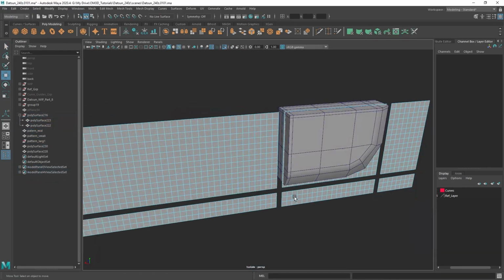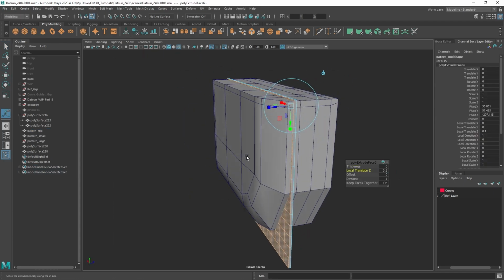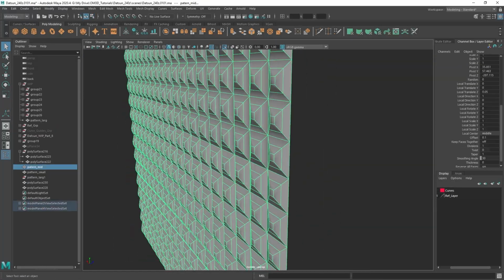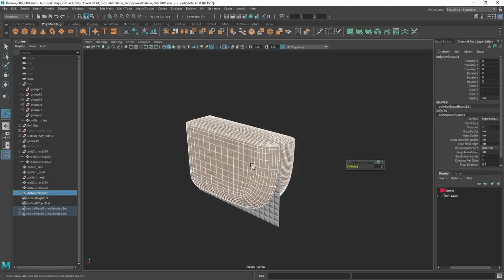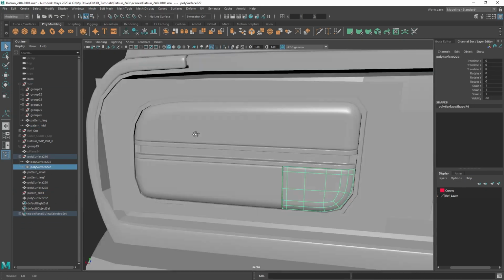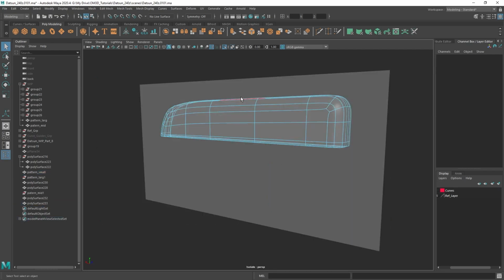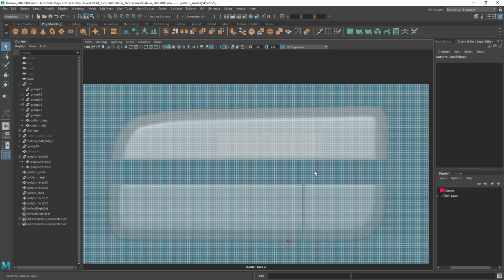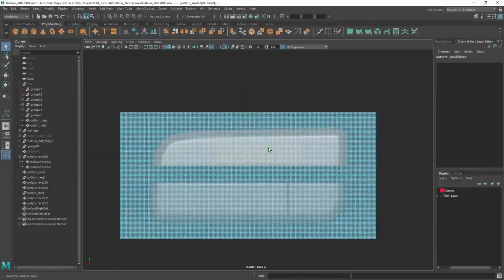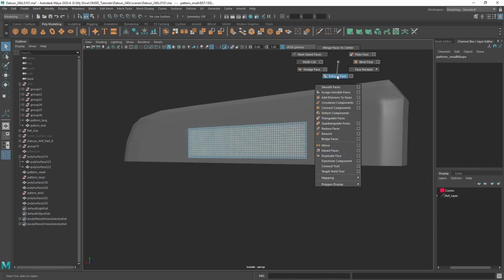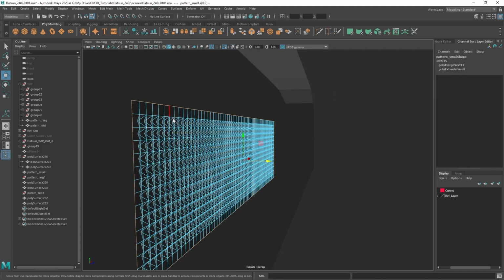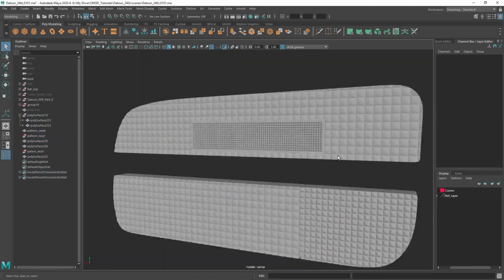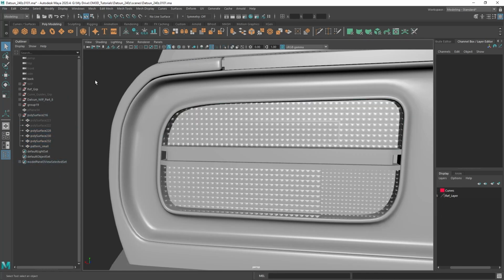And then I just move forward and do the same thing with the reverse light now. So I go through, extrude by face, double extrude, set the soften edge, smoothing angle, make sure everything looks good, create the boolean cutout for geometry, and then I go and add this last square piece that's just kind of an inset on that. These are the tiny little diamond patterns, and I go through and just use the nice triangle pyramid type effect. Clean up the geometry, make some final adjustments, and this is where we ended up.